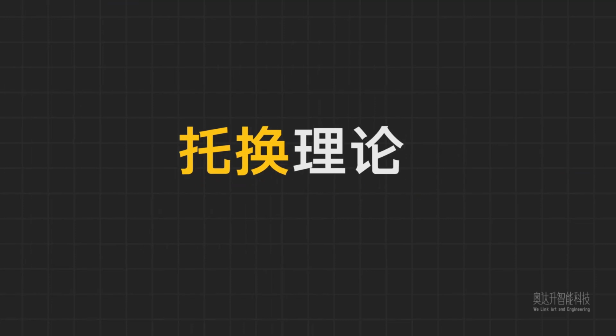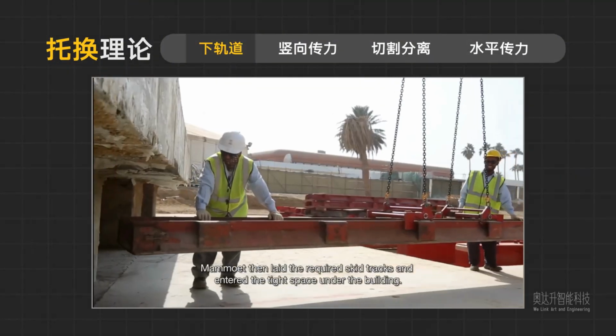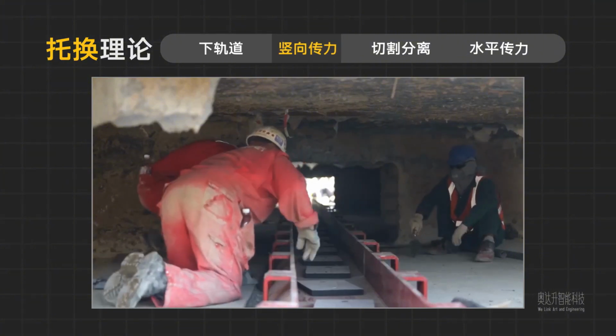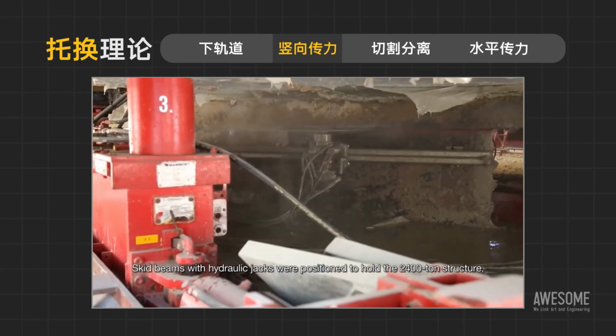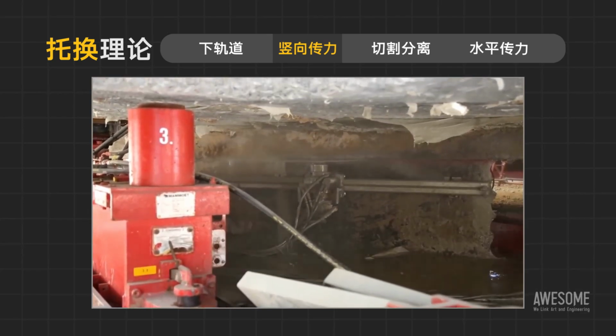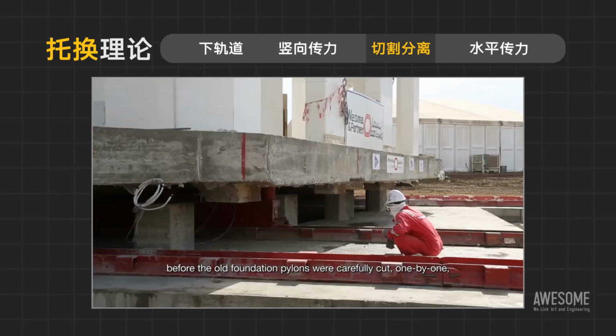In short, the overall translation of a building is to change its vertical force transmission system by setting up lower tracks and jacks according to the theory of underpinning. And then, cut and separate the upper structure and foundation, and move the upper structure to a new position by pushing and pulling.